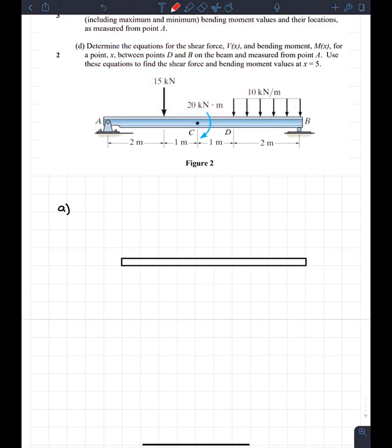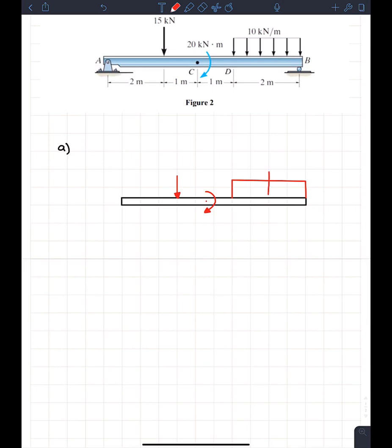So we're going to start by putting on all the external forces onto the beam. We see that we have a vertical load over here. We see that there's a concentrated moment, let's say somewhere right here. And then at the very end of the beam, we have a distributed load. I'm not sure exactly where I want to put this. We'll just put it like this. What I do for a distributed load in a free body diagram is I just draw the silhouette. That one looks kind of crooked, so I'm going to get rid of this and try to make it a little bit more straight. Again, we're not going to judge you if it's a little crooked. It's still a little crooked, but it doesn't matter. You guys won't judge me. We won't judge you. All right, and I replace it with an external force right in the middle.